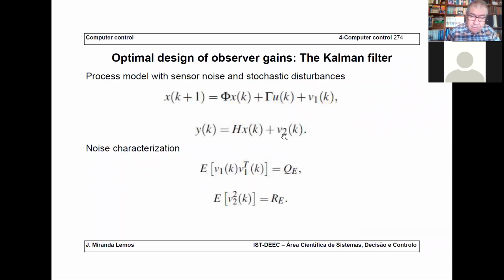White noise has a constant frequency content. That's why it's white. It is present at all frequencies. So you go on enlarging the bandwidth of your filter, and the optimal point is somewhere close to the situation in which all of the X's have passed. Because if you enlarge it more, noise comes, which is a bad thing, and you win nothing because there are no more components of X to pass, since all of them have already passed the filter. The Kalman filter does this in an automatic way. I'm not going to write expressions here, but you can have these ideas.